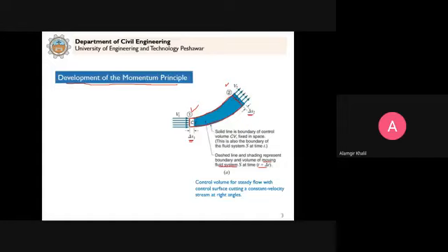So now, why do we consider this control volume? Because it helps us to analyze the problem. It simplifies the analysis. Clear? That's why we use this concept in fluid mechanics analysis. Now in this case, you see that this control volume here contains the fluid at time t, and then there is an inflow of the fluid at this point here at section 1.